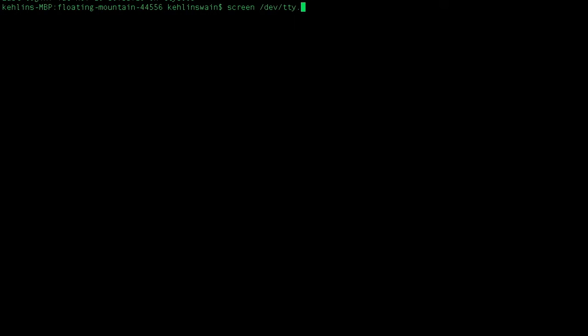Okay, and so the commands, you can pretty much follow the same commands I'm doing: screen /dev/tty. And this part here, USB, it will be different for you. So what I press is tab to figure out what USB serial port to connect to in order to access the Intel Edison. And then the baud rate that we want to connect on is 115200.